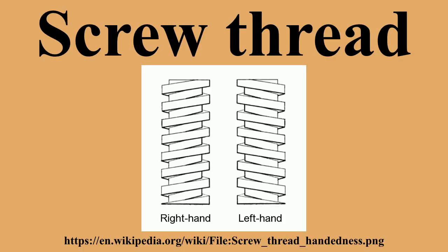Left-handed thread applications include where the rotation of a shaft would cause a conventional right-handed nut to loosen rather than to tighten due to fretting-induced precession. Examples include the left-hand pedal on a bicycle, the left-hand grinding wheel on a bench grinder, the lug nuts on the left side of some automobiles, and the securing nut on some circular saw blades.